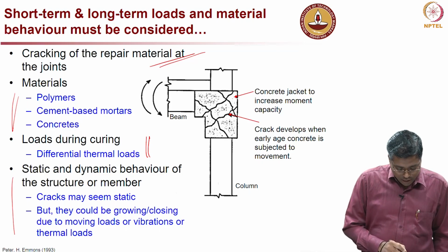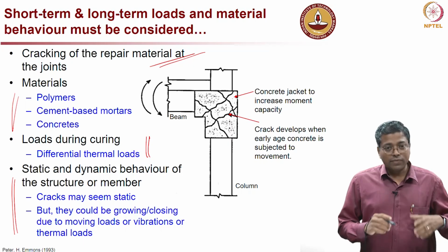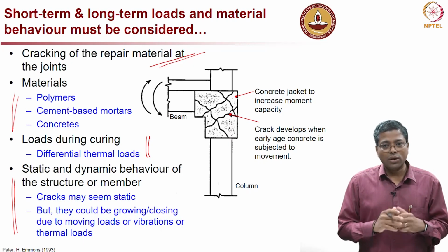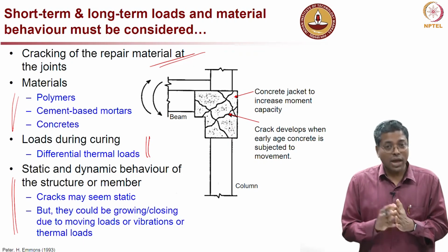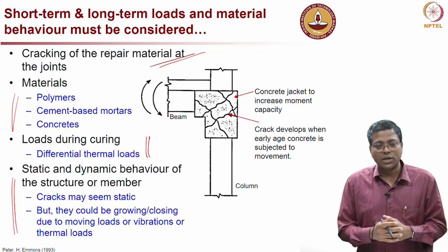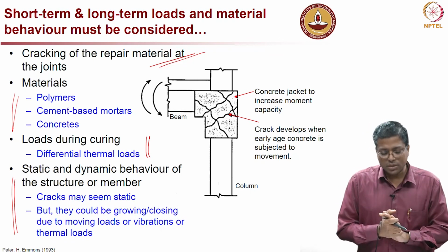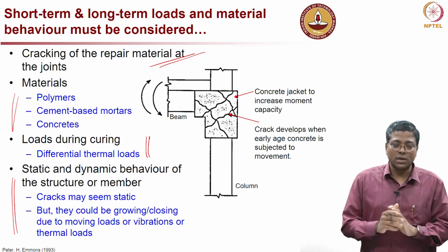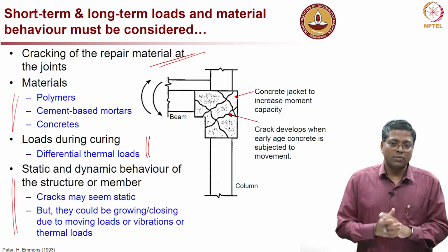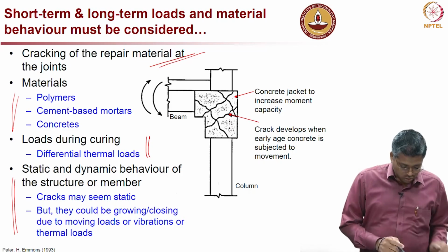Now, static and dynamic behavior should be looked at. If some crack is there, it might look like the crack is not growing, but it may actually be growing, or it may actually be closing and opening in case of fatigue loads. So, all these have to be thought through, and the material selection is very, very important. It is not only the structural system design, but the materials which we use should actually take those loads also.